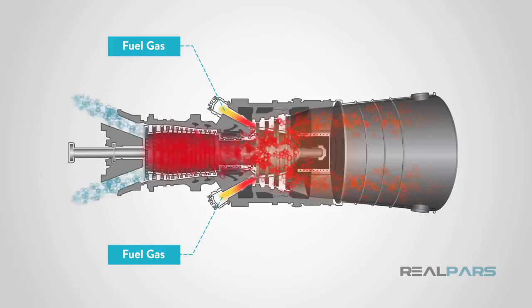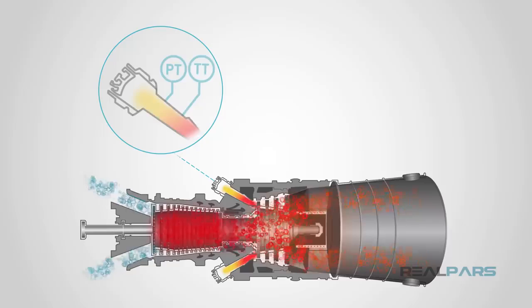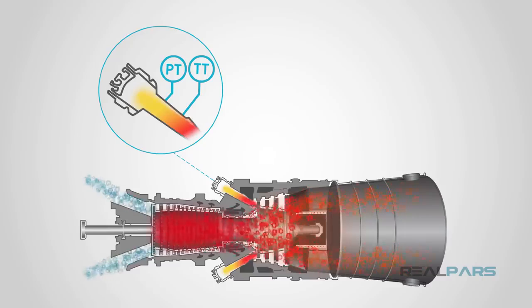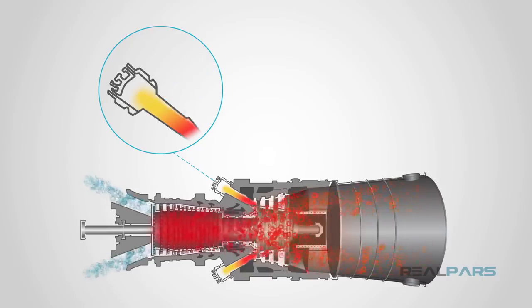The manufacturers need to know the details of fuel gas, and only based on its characteristics can they guarantee the performance of their gas turbines. Also, the pressure and temperature of fuel gas are monitored during normal operation of a gas turbine. There are different technologies in properly mixing the air and gas and making efficient combustion from manufacturer to manufacturer.